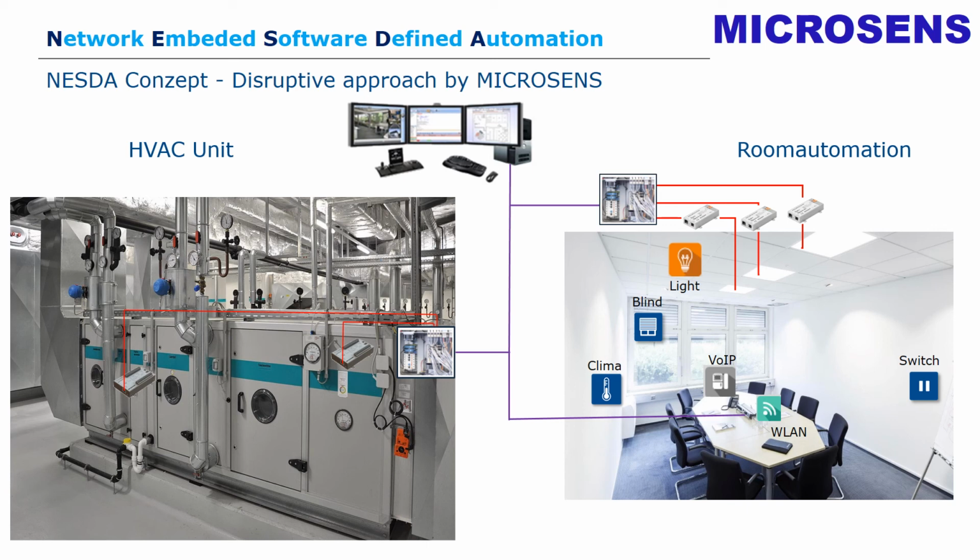This means we only have to cover the power connections for the ventilating device, which could be covered directly from the power distribution cabinet from the floor, and all the automation functionality is covered by this box. So if I have many of those devices, I don't make a dedicated planning of cabinets for each device, but I use for each device its own smart distribution box, and to do this is quite a lot easier than making a dedicated planning for cabinets.